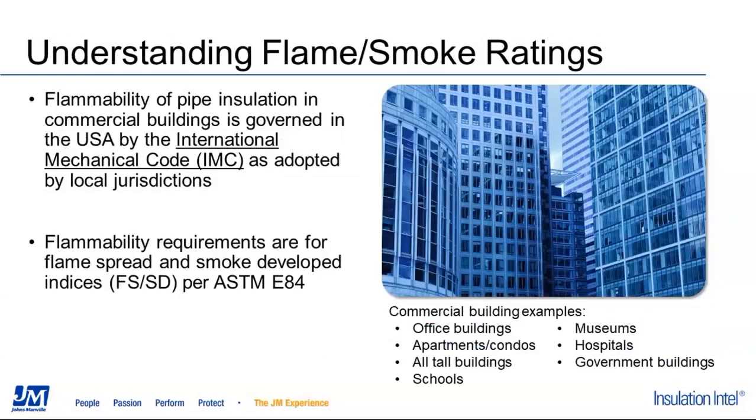Now let's take a look at understanding flame and smoke ratings. When discussing commercial building chilled water pipe insulation, it's important to understand the required flammability performance. Flammability of pipe insulation in a commercial building is governed in the U.S. by the IMC, adopted by local jurisdictions, and interpreted by local authorities that may have jurisdiction.